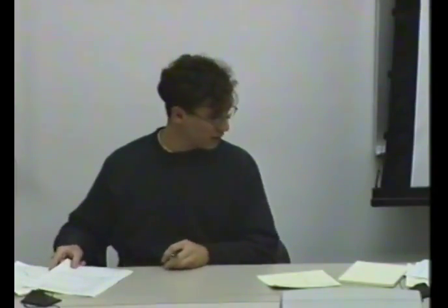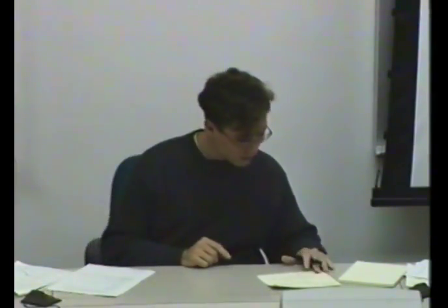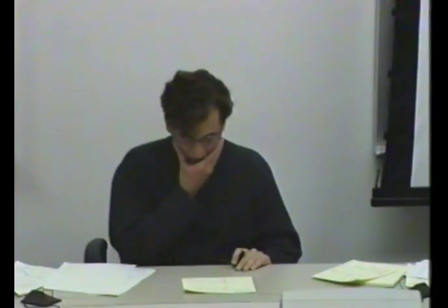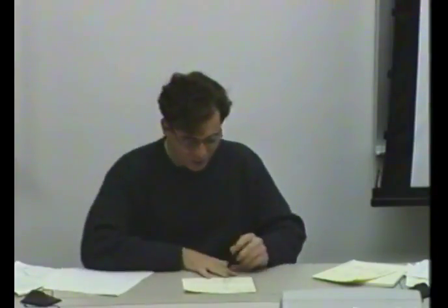From now on, I'll follow the lecture notes a little bit more closely. I'm almost done with my notes here. The first term is so easy that Professor Bode didn't care to put it in the lecture notes. It's just the k term here. It's really easy because there is no frequency dependence to the magnitude and phase of this term. None at all. So really, the Bode plot consists of straight lines. It's a piece of cake.